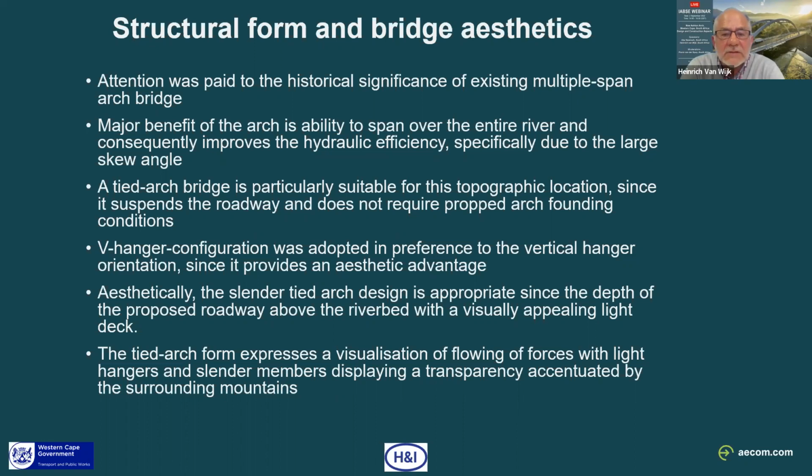Because of the suspended roadway with reduced deck depth, we could achieve tie-ins with the approaches and also provide improved hydraulic clearance. A V-hanger configuration was adopted in preference to vertical hangers to also assist with the aesthetic appearance. And we believe the visually appealing light deck, especially viewed from the side, expresses itself nicely, but it also focuses on the force configuration of the structure.